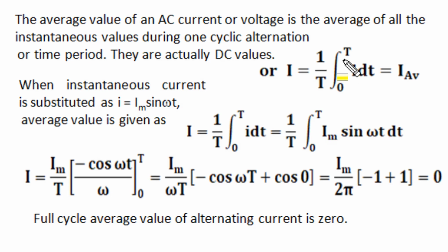So when an alternating time varying current is integrated for a certain time interval and that integrated result is divided by the same time interval, we get the average value of current. The average value of current is that steady DC value which transfers the same amount of charge as this alternating current is producing. So we can say the average current of alternating current is the equivalent charge transfer capacity of AC in terms of DC. For the sinusoidal standard current, i equals Im sin omega t, where Im is the amplitude or peak magnitude of the sinusoidal time varying alternating current.